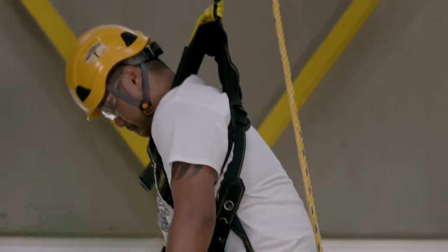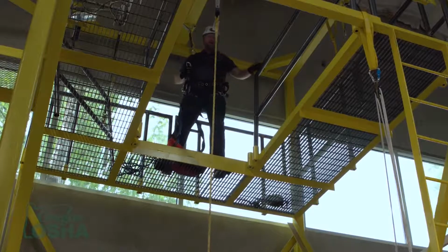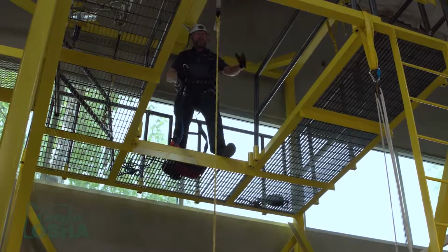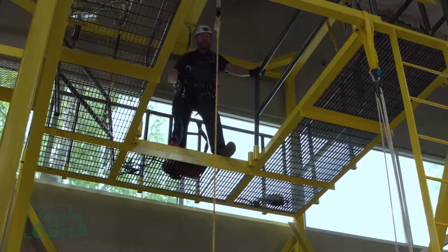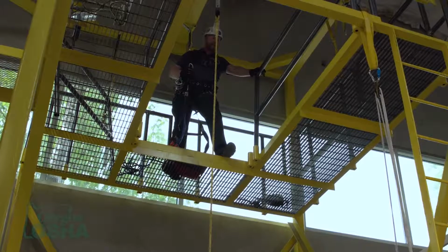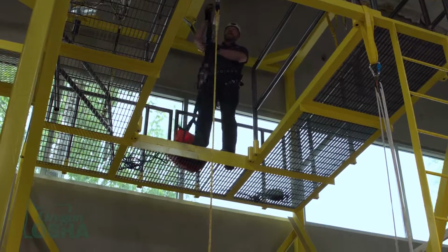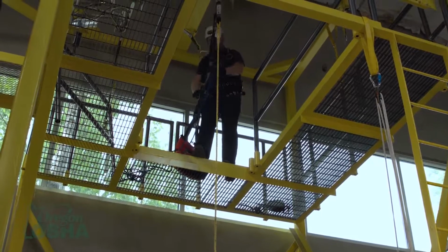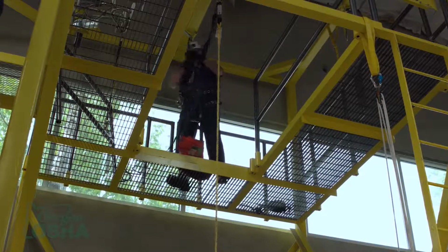So at this point, in rescue, we want to look for an anchor that's at least 3,000 pounds strong or 5 times the weight of the worker. In some cases, if you can attach to the same anchor that's just fallen off of, that is perfectly acceptable as well, as long as it's in good condition. So at first, I'm just going to connect the ladder like this, and then I'm going to drop the ladder down. And I'm going to, of course, let my victim know that it's coming.